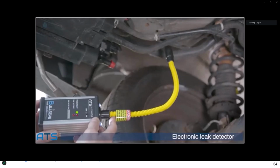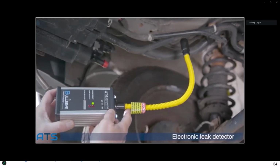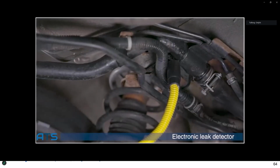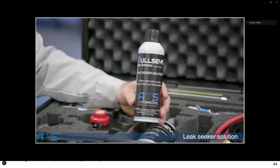Using the electronic leak detector, slowly sample the area suspected with the leak. The leak detector LED will illuminate as you move toward the leak. The frequency of beeping and the LEDs illuminated will increase as you move toward the source. Once the base location is identified, use the leak seeker solution to hit the bullseye.